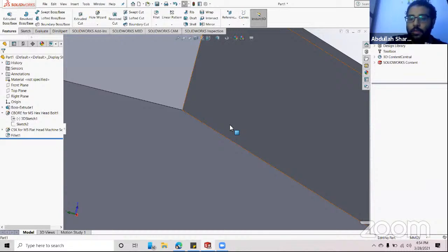For me as a designer, I'm doing fillet for two different things. The first one is to reduce these weaknesses that are made by the angle, and the second one is to reduce the hardness of the edge. As you can see, if I have an example of something, okay, you can see this stapler here.